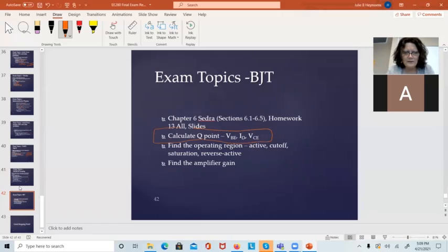And that goes back to that one slide I keep pointing to and saying, I got everything on this slide. There are 4 equations and 4 equations. There is active: VBE equals 0.7 volts. If you know that and you can apply it, and you can use Ohm's law, you'll probably be okay. Saturation, which we don't use too much anymore, because that's for digital circuits, and they're not good digitals. They're better analog. VBE and VCE equals 0.2 volts.